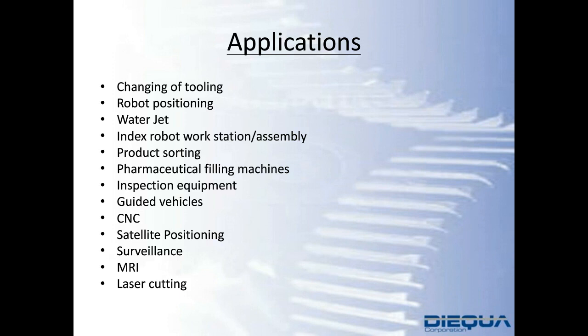Guided vehicles, right? In these cases, you're having applications under a frame, under a platform, where ideally you'd like to drive the wheel individually so it behaves and maneuvers in the most compact manner. Directly mounting the wheel onto the robot flange eliminates any axial distance that you would get from coupling from shaft to shaft.